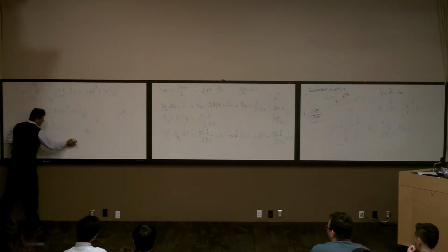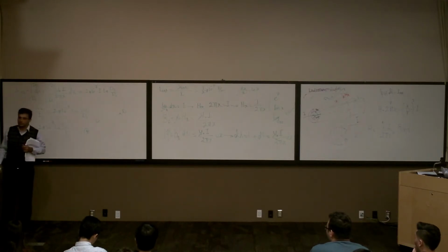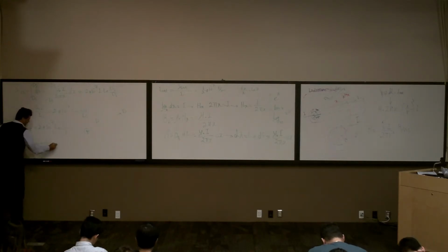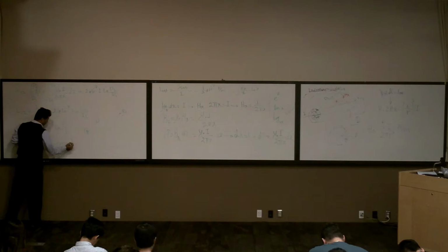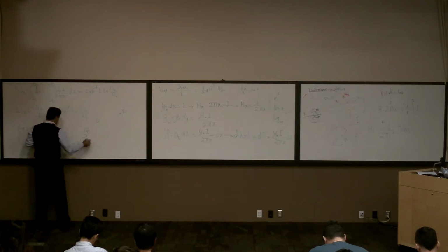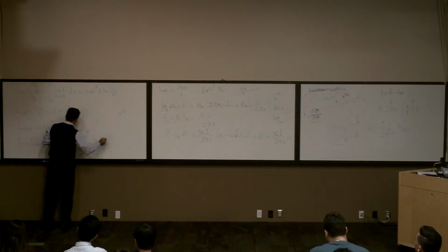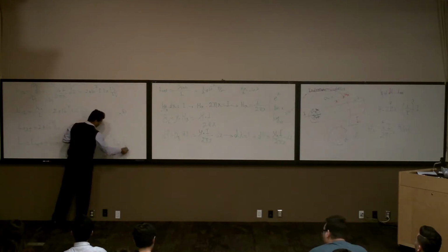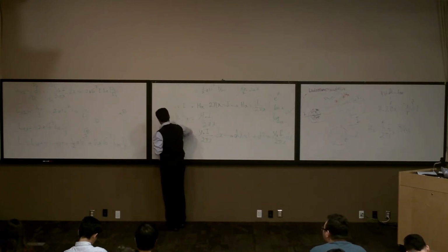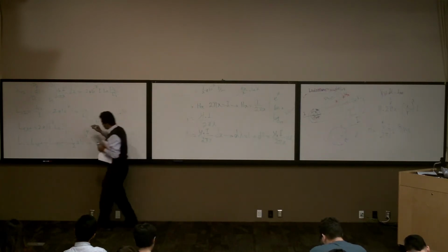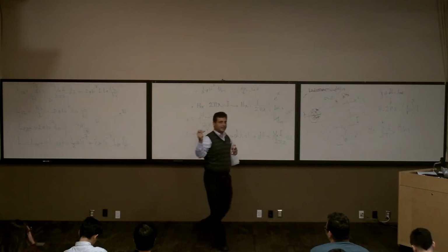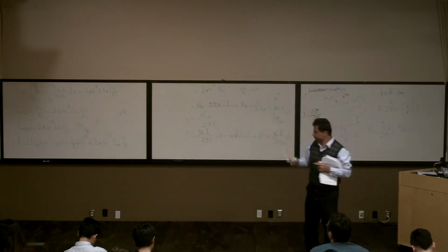So we calculated L external. Now how much is the total inductance? L is going to be L internal plus L external. So basically it's going to be 1 over 2 times 10 to the power of minus 7 plus 2 times 10 to the power of minus 7 ln of D over r. Now let's simplify this equation a little bit. Oh, I forgot here, this is Henry per meter again. Keep in mind, this is per unit length, for 1 meter of the cable.